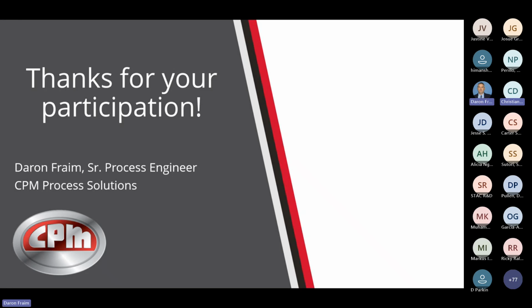Which metallurgy is best suited for screw elements for reactive extrusion and conventional extrusion? I don't know if there's really a key difference. The main thing to understand is what your reactive components are and whether they are corrosive. That would be my suggestion. It depends on the type of additive, and what type of monomers or reactive components.